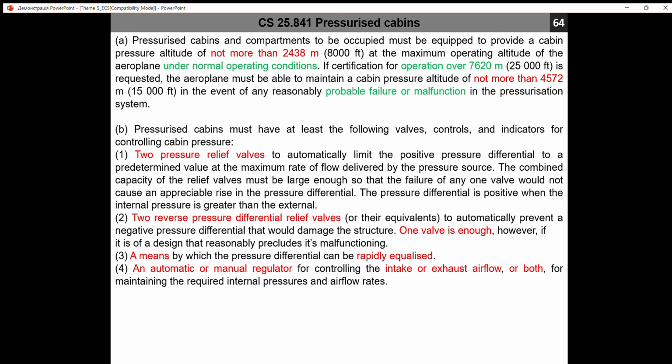So that's an outflow valve, but something may go wrong and you need to protect your system from malfunctions. For these purposes, we have not less than 2 pressure relief valves. They are fully automatically operated systems. They don't have any controlling elements. They just keep a balance between the pressure difference and spring loads.